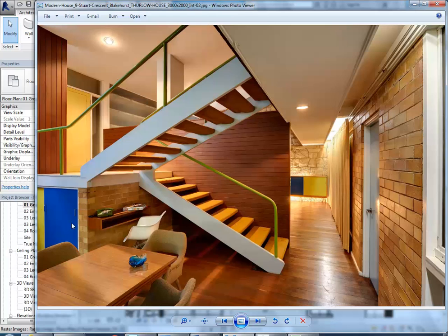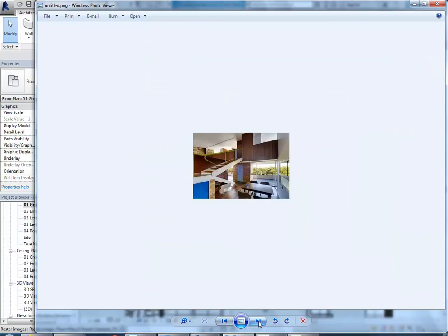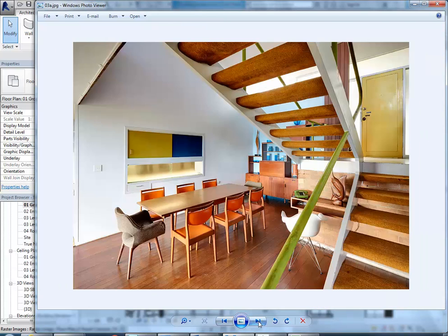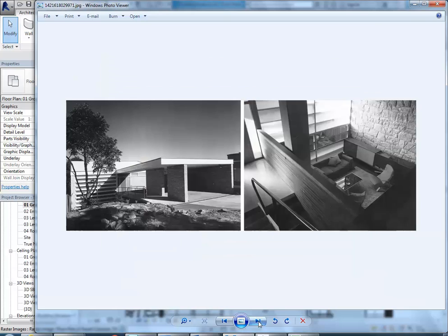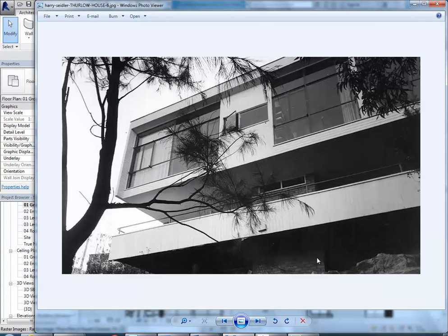Yeah, and look, it's a common assumption that he might have tried to keep things as open as possible, but I'd say, and also, the giveaway, the bricks kind of match it. And then looking at the exterior, if it was an add-on, why would they extend the brick walls down to act as a footing? Because that's what they're doing for the building going into the sandstone. So I think that's your answer.